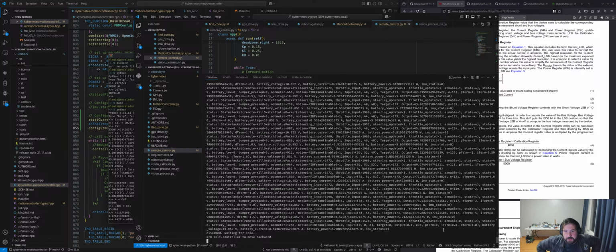Realistically, the fact that you can do a 4K video encode and run an object classifier at 60 FPS on a dedicated device, in the span of 4 to 5 watts, that's pretty cool. I guess a phone SoC also draws like 5 watts at full tilt, so maybe it's not actually so impressive. But yeah, so there we go. Just idling there doing nothing, it pulls a watt, and then running a lot of its hardware at the same time, it pulls another 3.6 to 4 watts. Hopefully that answers your question, Danish.